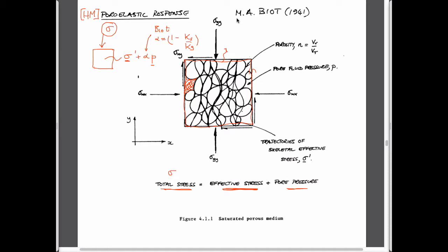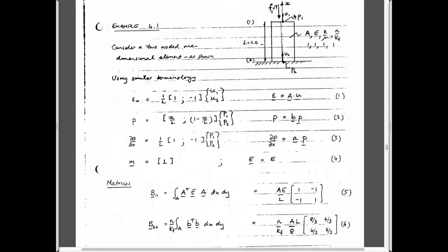But the most broadly accepted theory, when you have compressible constituents, in other words, where you might have compressible soils and also compressible fluids, is by Biot, referred to as Biot poroelasticity from 1941. And so what we'll do to address this, since we're talking about things in finite element format, is we'll introduce it in finite element format, which is what we'll spend the first little time doing.